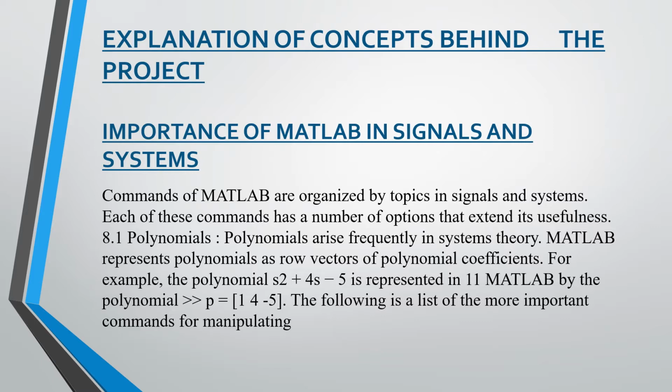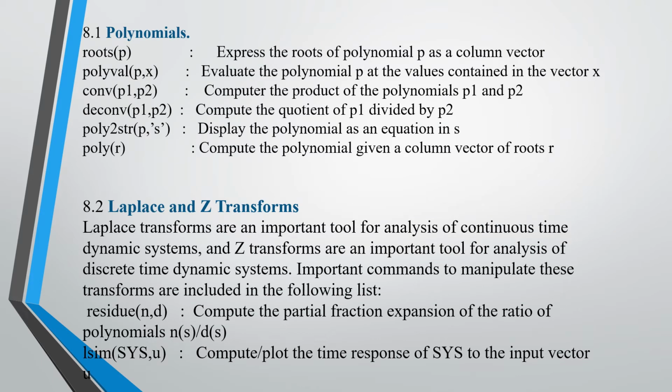For example, the polynomial s squared plus 4s minus 5 is represented in MATLAB by p equals the bracket 1, 4, minus 5. The following is a list of the more important commands for manipulating polynomials. Following are some commands on the screen.